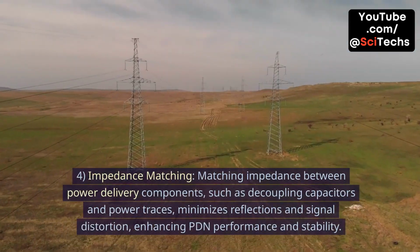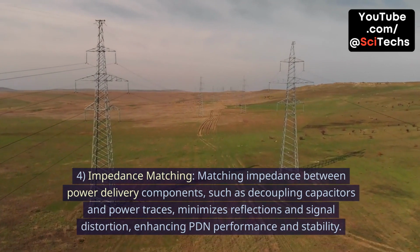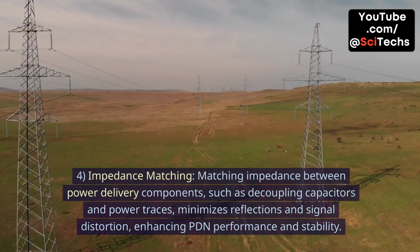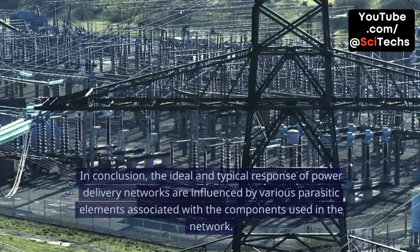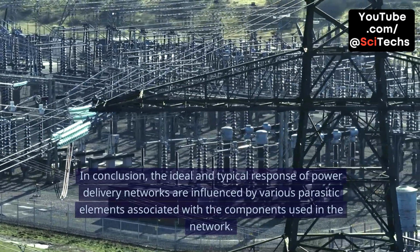4. Impedance matching. Matching impedance between power delivery components, such as decoupling capacitors and power traces, minimizes reflections and signal distortion, enhancing PDN performance and stability. Conclusion. In conclusion, the ideal and typical response of power delivery networks are influenced by various parasitic elements associated with the components used in the network.